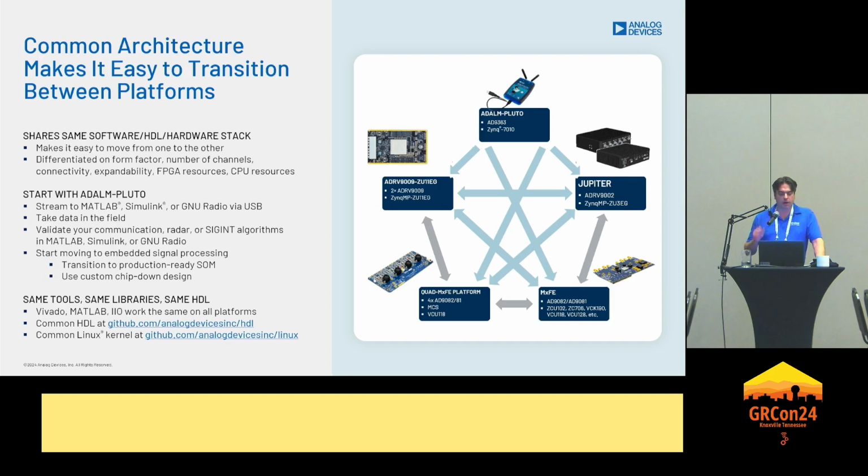So the common architecture makes it really easy to transition between platforms, since our open source reference designs are all built on the same stack and technology and infrastructure. So you could go from an ADALM-Pluto to a 6 gigasample multi-channel RF digitizer without actually relearning anything. And even the HDL IP cores, the transport layer core, it's exactly the same. It has the same register map, uses the same Linux driver, and things like that. So everything is open source and publicly available for all these reference designs.